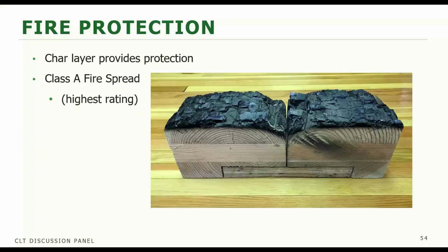So I know Lori talked about fire protection a little bit. As CLT burns, it provides a char layer. That char layer kind of helps slow that fire growth. Oftentimes what we're doing as of now is just adding mass to that wood so that once we burn this wood for a couple of hours, it's still going to be structurally sound once it's done burning.